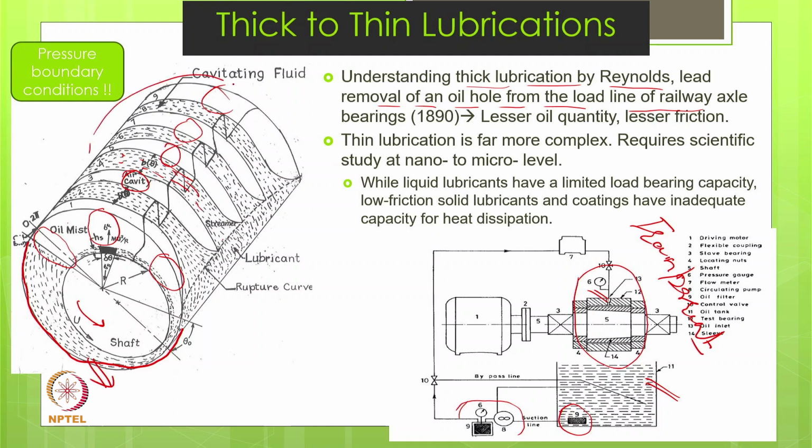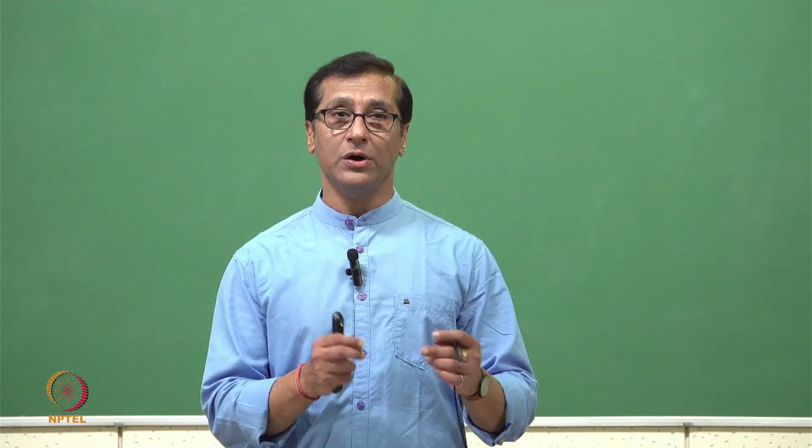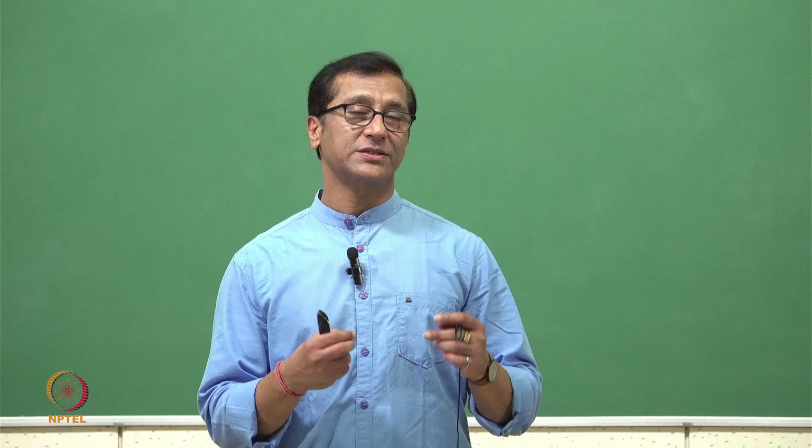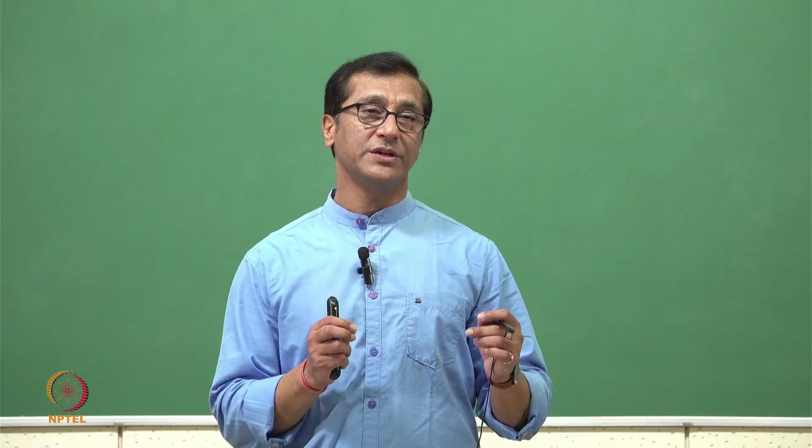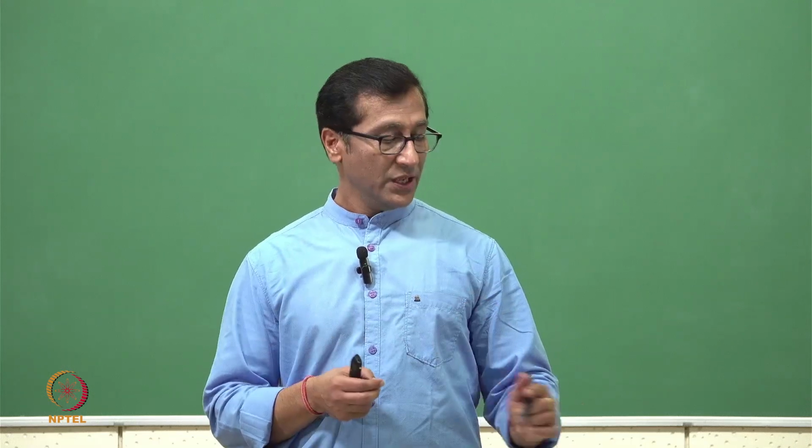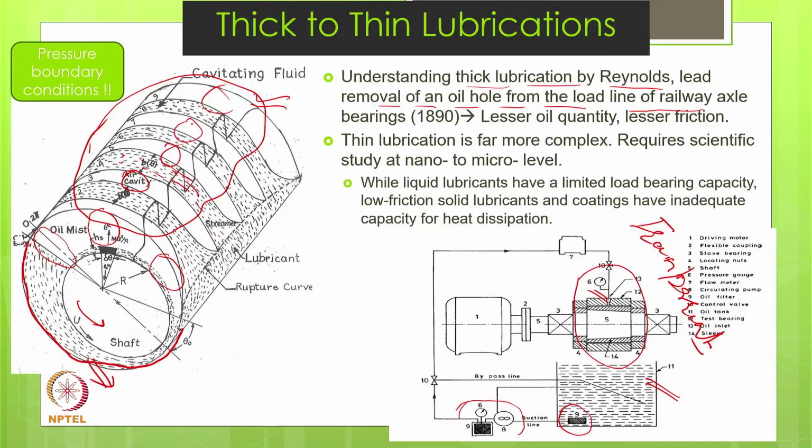However, if we are providing a lubricant from this surface or this portion, that will be advantageous. So making the oil hole, oil groove, at which portion of the bearing is really important. If we make the oil hole in this portion, then it is advantageous. That's why we are trying to solve this kind of problem. Overall results are favorable.